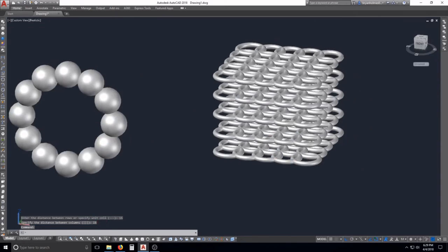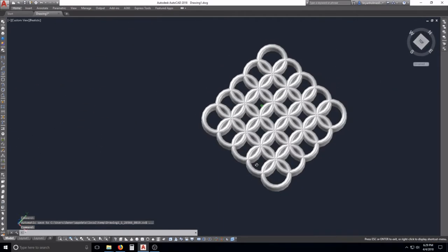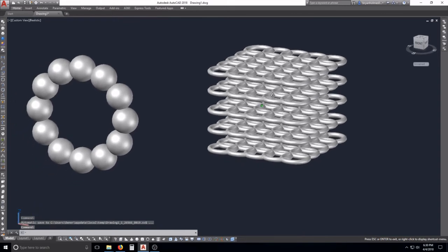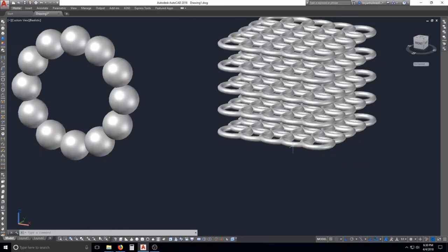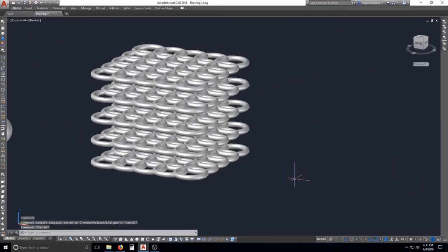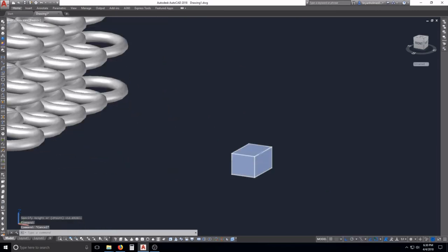And obviously I did not separate them far enough, but nonetheless you see where, because apparently it was larger than 15. That's why it was important to know, when you're using this particular function, how big your object is. We can do that real quick again with a square. Squares or cubes are a little easier to do. We'll try to do it a little quicker. So we'll go there, just bring her up. So we'll go to 3D array, and you get a better result.